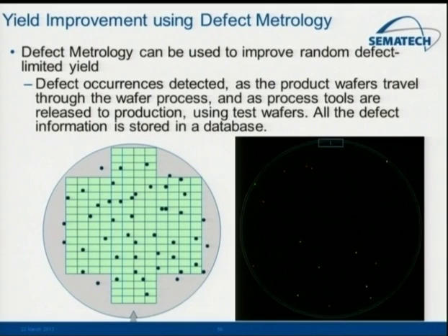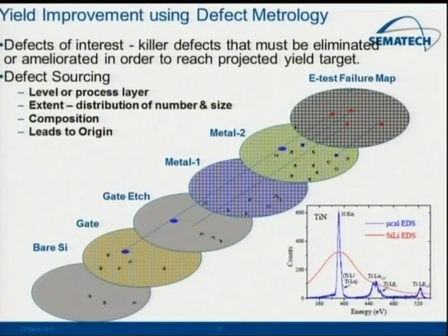Statistically, you can calculate that. So ideally, you're looking for wafers where it's a low number of added defects. You know where they are, and you can react to them. And there are several different techniques for doing that, and I'll explain those in the next few slides. But first, here's the slide that explains, if you have a few defects on your starting wafer, you print your gate structures, you do the gate lithography, the gate etch, you start to build up.